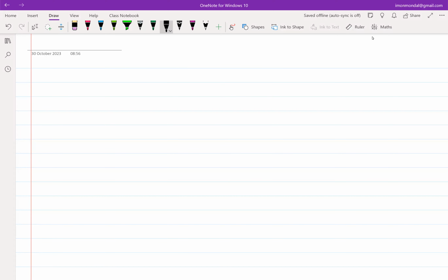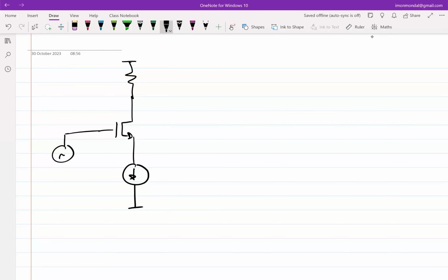So we saw a couple of architectures, and one of the architectures that we were discussing before we stopped was this, in which the constant current source was, firstly, you need the resistor at the drain because it's a common source amplifier, otherwise you will not get any amplification. And we were sticking a current source at the source, and at the input side, obviously, at the gate, you have the bias plus the input.